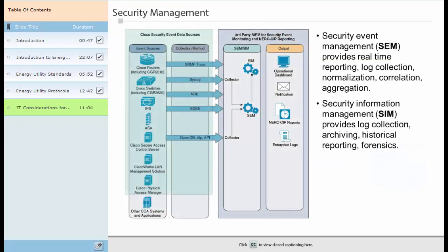Substation security management addresses security requirements from 3 perspectives: security service provisioning, network security monitoring, and regulation standard compliance. For each of these security management areas, substation network availability and attack resilience are the primary objectives. Additional network data protection requirements include data integrity and data confidentiality. Security Event Management, SEM, is a component of substation security which processes security-related event data in real time for threat management, malicious activity, and incident response.